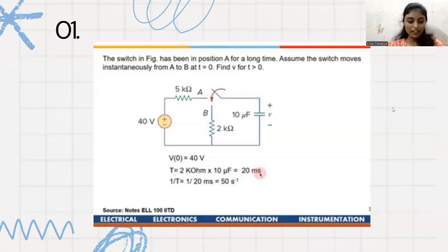The given resistor in the diagram is R is equals to 10K, and the capacitor is C is equals to 40 microfarad. Internal voltage V is equals to 0. So the time constant tau is equals to RC is equals to 10,000 ohms into 40 into 10 to the minus 6 is equals to 0.4 seconds. Discharge of the capacitor is discharge of the RC circuit.